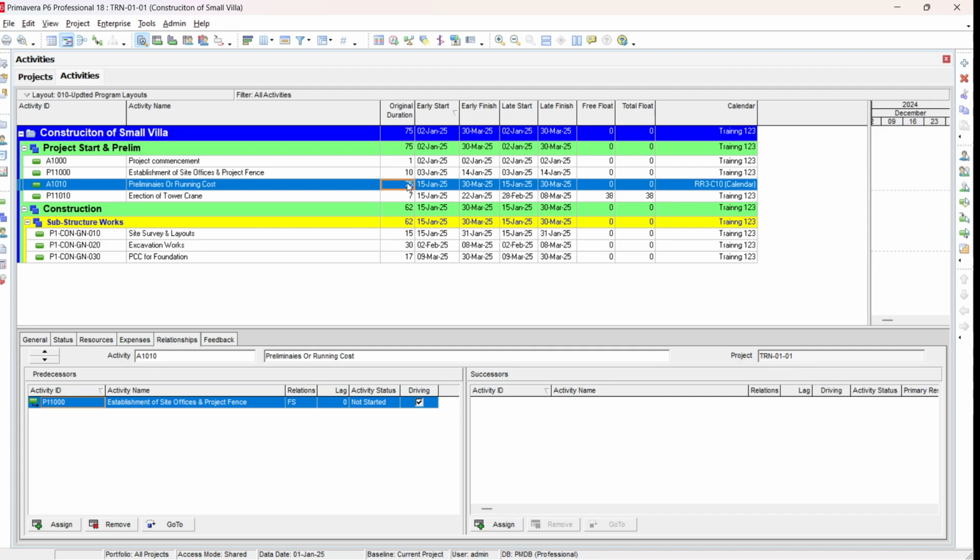So normally, when defining the calendar in our projects, we have to define two or three calendars. The same way we define here. One calendar is for the preliminaries, which does not include any holidays or anything. It is going overall the project duration. Other is for the working calendar, which is for the site execution, and which is for the contractor. Contractors normally have 1 day holiday, or sometimes they don't have any holiday, and they have 10 hours working days. But you have to assign there the holidays, the gazetted national holidays, and the reduced working hours if there are any in the country. And one more calendar we have to assign for authorities.